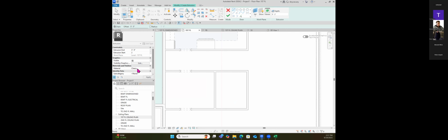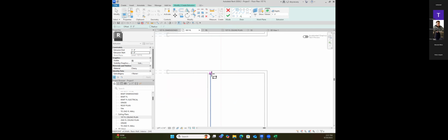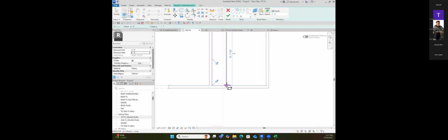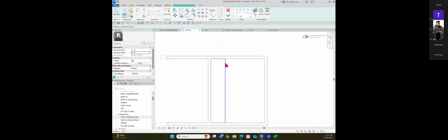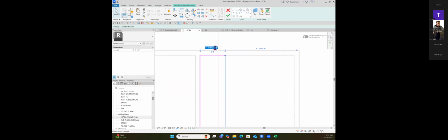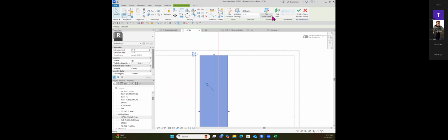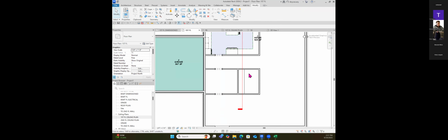So it'll be a foot thick instead of 2 inches. And then I just draw it from here to there. And let's see, how wide do I want it to be? Click here, make it 2 feet. And we'll say okay. Now let's just go look at the 3D and see what I just did.